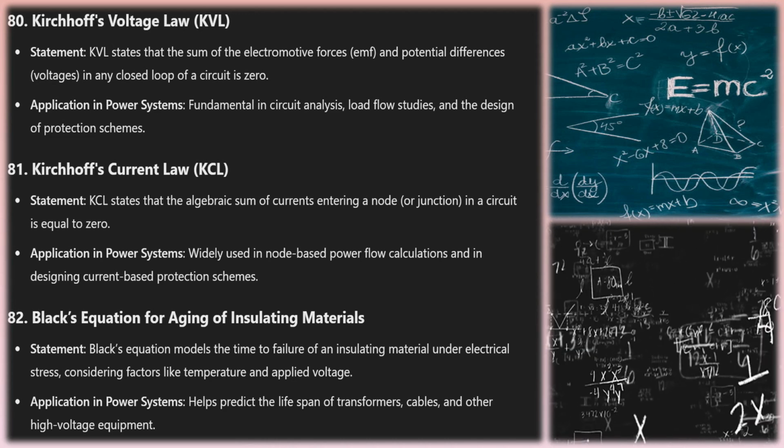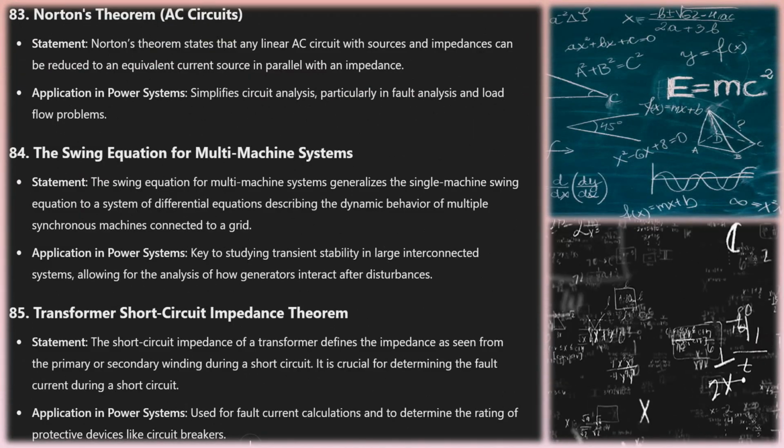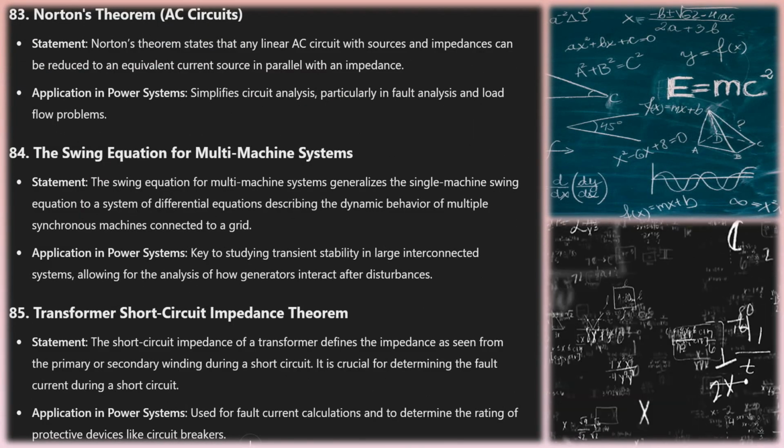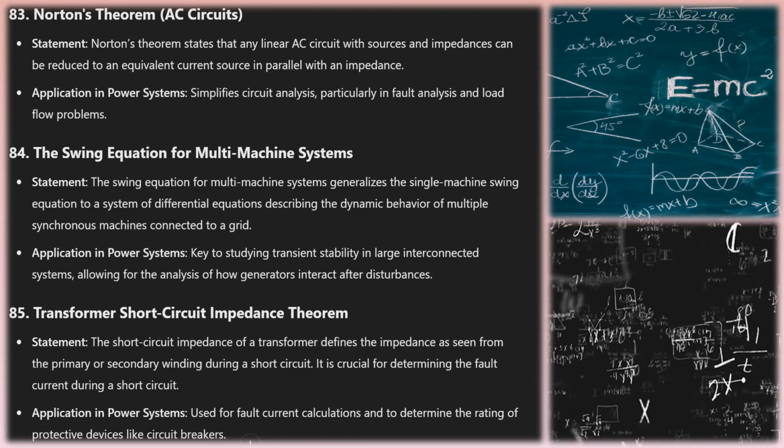Modal analysis theorem. Modal analysis involves decomposing a system into its natural modes of oscillation, each described by an eigenvalue and eigenvector. Application in power systems: used in small signal stability analysis, particularly in detecting oscillatory modes in power systems and improving damping through power system stabilizers (PSS).